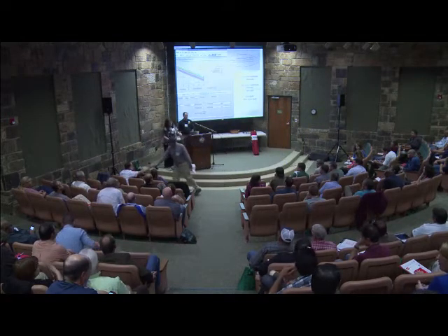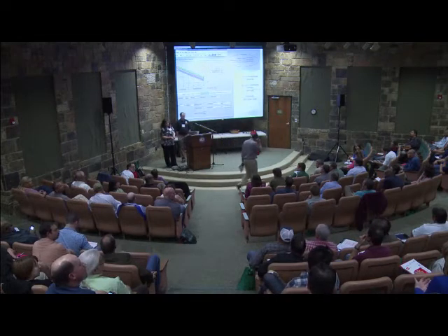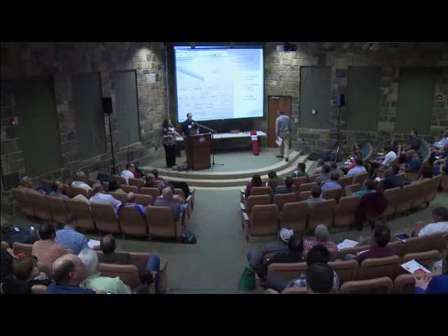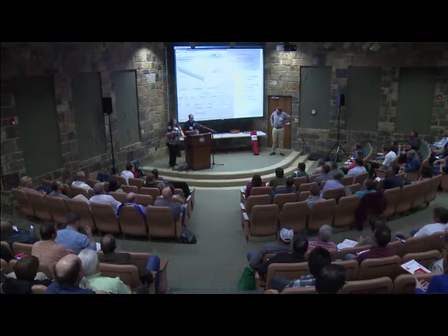Was any interpolation allowed if you have a 30-foot buffer? I mean, are you allowing any interpolation, or are you assuming? I'm asking the hard questions. So if you have a 30-foot buffer and they require a 50, then you have to get alternative controls to get that extra 20 feet. Right, so it's just the 20 feet you're looking for at that point, not the full 50. Yes.